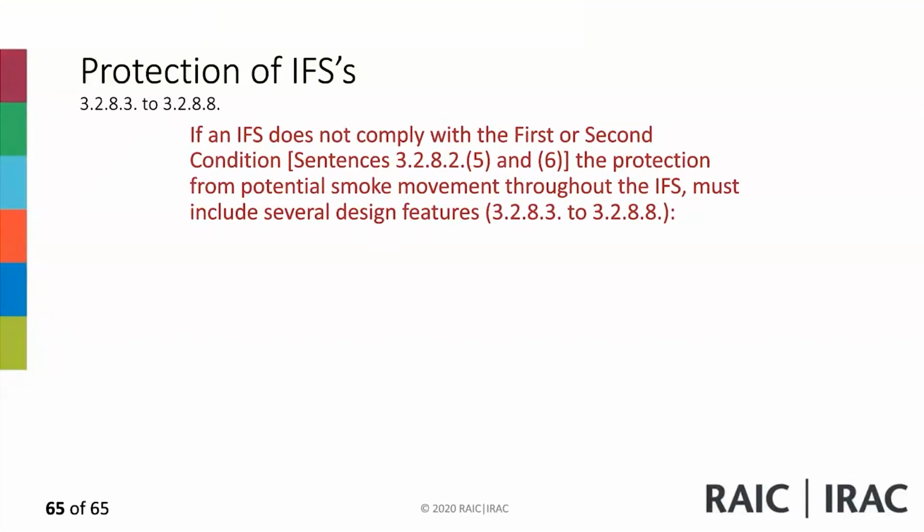So if you have a process and you have multiple openings as part of the manufacturing process, you don't need to provide closures. Typically, we provide closures for openings for fire separation, whether they are horizontal or vertical. In this case, you don't need that. You need the openings as long as they are essential for the manufacturing process.